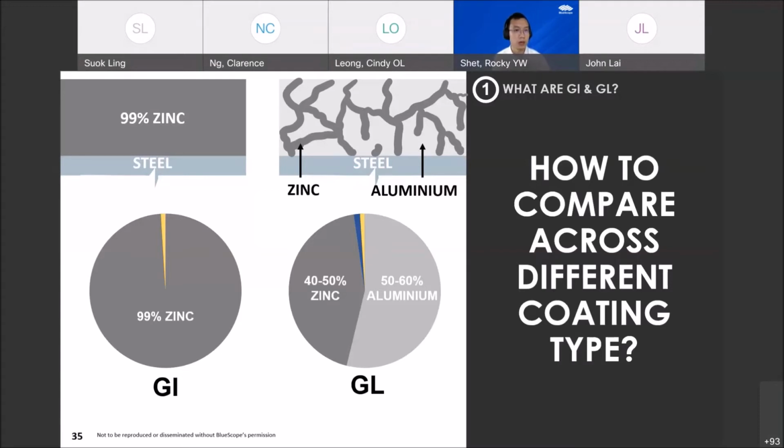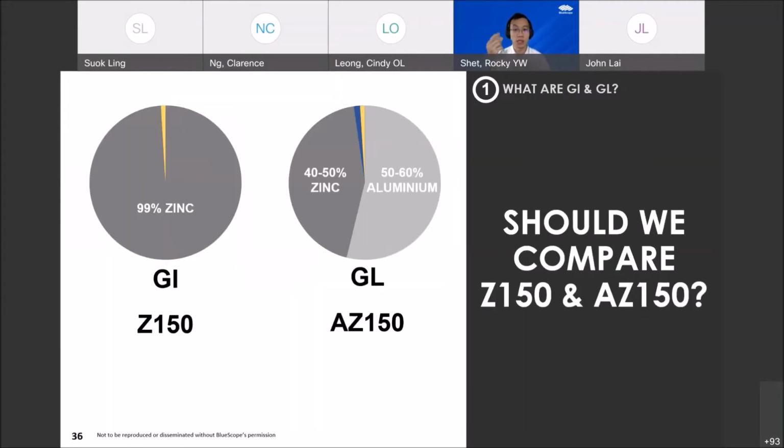When you classify GI and GL, it is still not very specific, because there are actually many types of thicknesses, right? So 10 kg of rice is different from 5 kg of rice, right? But it's still rice, right? But just one will last you longer than the other one, right? So same thing over here. GI and GL are just a generic term describing these two different types of galvanic coating or galvanic coated steel. But there are different coating thicknesses, right? So most often people again would take it for granted and just say, oh, just keep it galvanized steel, would not rust on, right? So without any further context.